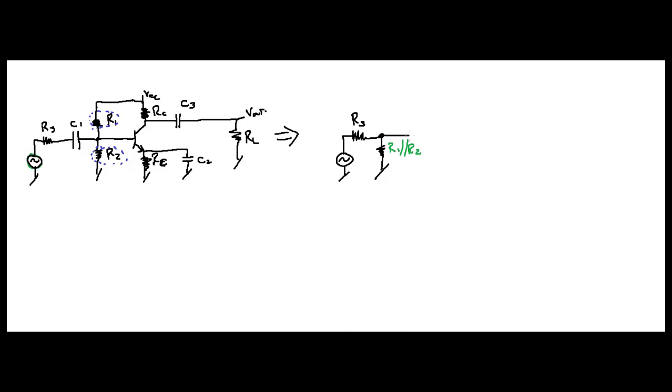Now, if we keep on going, we're going to come to your transistor, right? Now, let's talk about your emitter. Over here, you have this capacitor, don't you? And what do we say at high frequencies? This capacitor becomes a short, and this is bypassing your resistor. So nothing's going to see that resistance. So basically, this emitter at these high frequencies can just be thought of as going right to ground, right?